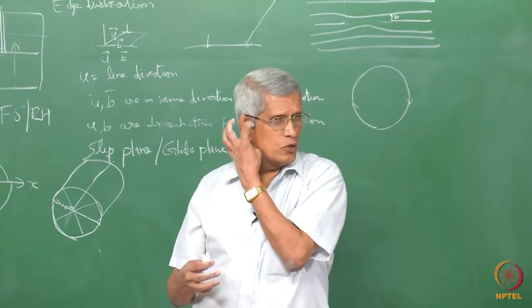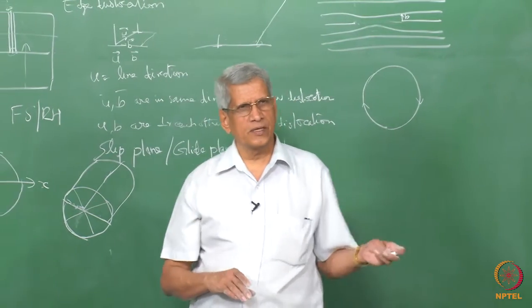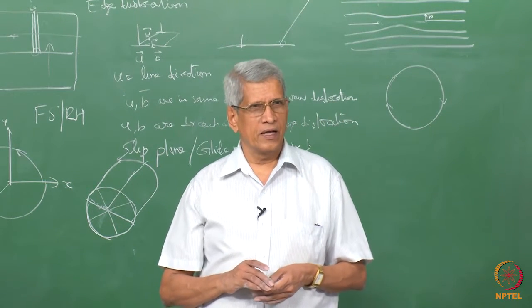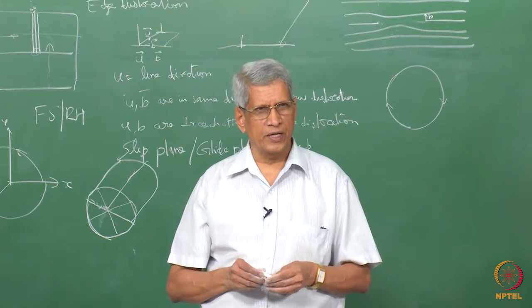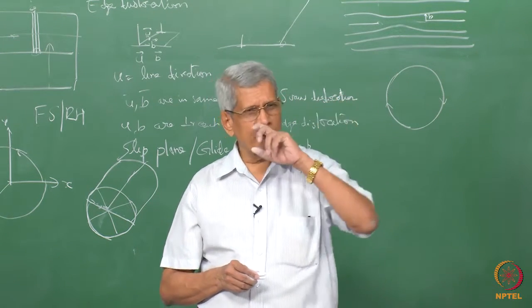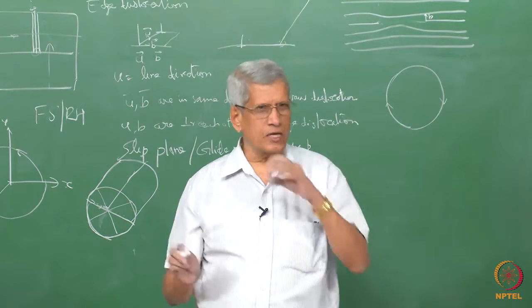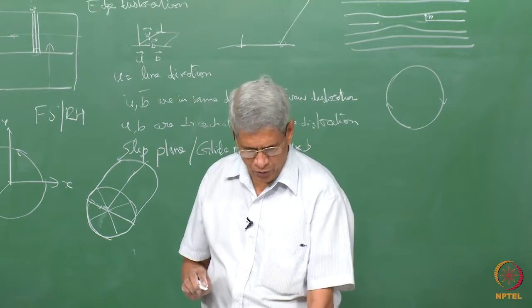This essentially indicates that it just cannot end within the material. So in a polycrystalline material, the dislocation begins and ends from one end of the grain to the other end, from the boundary, so that the dislocation cannot stop within the material. This is one thing which one should always remember.